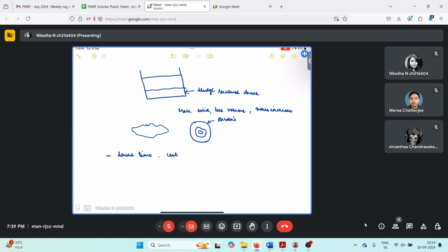Now, what happens in an aerobic condition? Your BOD will be removed, mostly carbonaceous. And nitrification will happen. Okay? Nitrification is what we just discussed. So nitrification is where ammoniacal nitrogen is getting converted to nitrites and nitrates. So when you have a densely packed sludge, the topmost layer is going to be aerobic.